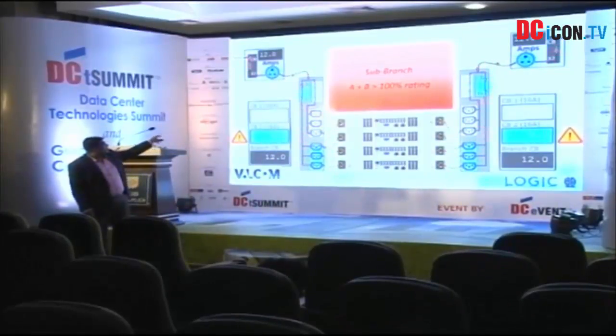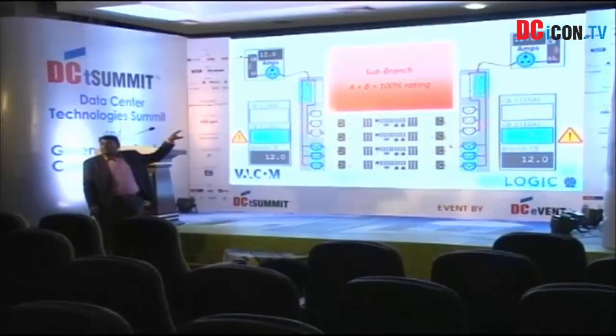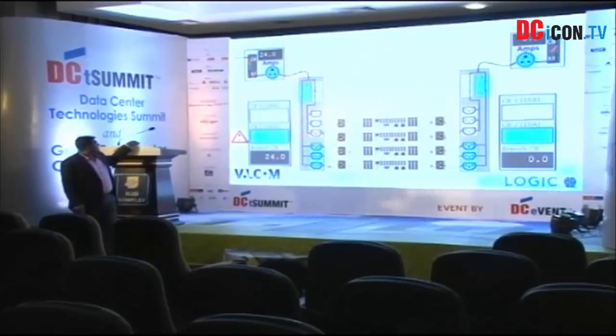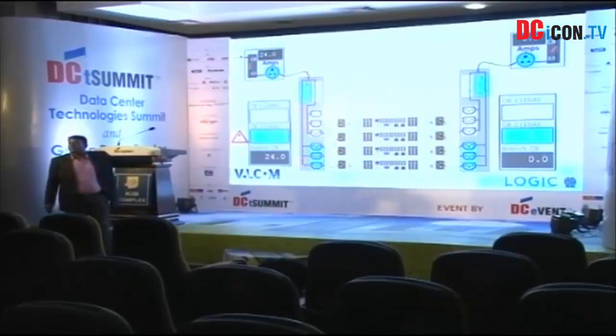If you look at the PDUs, you have 16 amps and 16 amps, two circuit breakers, right? So if you transfer the load to the other side, on the A source, if you look at circuit breaker B, meaning 1 and 2, the second one is 18 amps. But the rating of the circuit breaker is only 16 amps. So this is actually a poor design. Or probably when the IT manager is loading the servers and connecting to the power cord, they normally make these mistakes. So how do we rectify this?